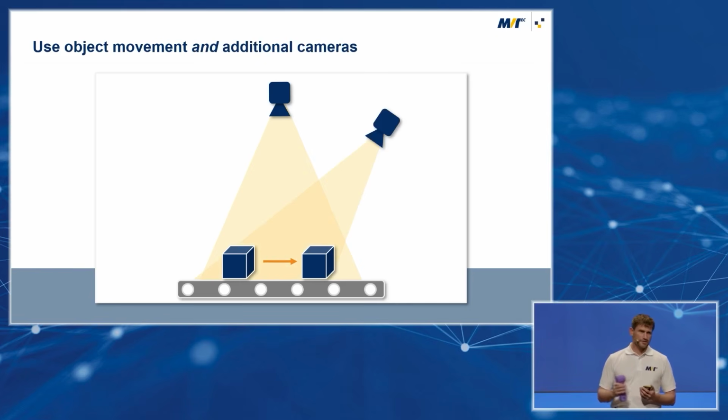What about adding in this system another camera from a different angle? Having the same scenario, we have 2 calibrated positions. The field of view of both cameras is on both positions. So as a result, we gain with 2 cameras 4 images. This will bring us much higher accuracy, and also a much higher detection rate if there are many parts in this scene. Maybe some parts are hidden, occlusions. 2 cameras will solve these problems mostly, to see all the parts.